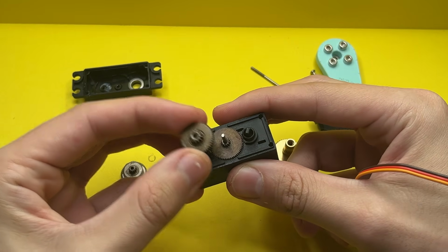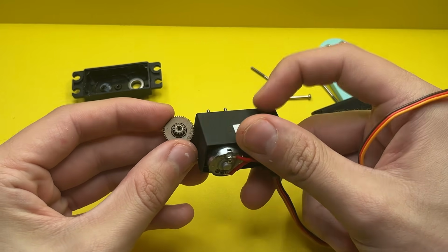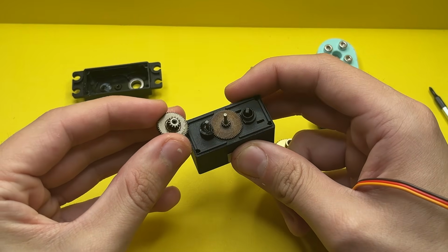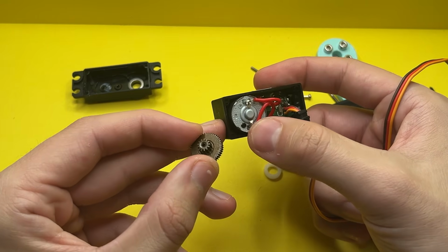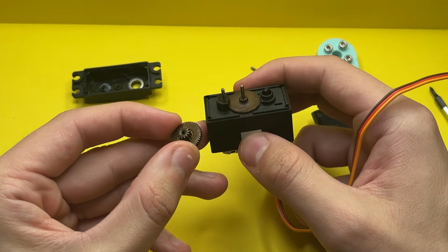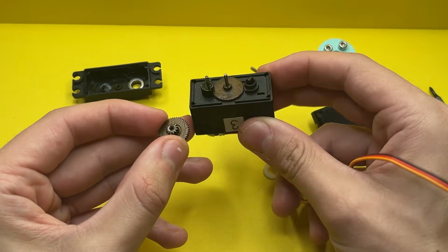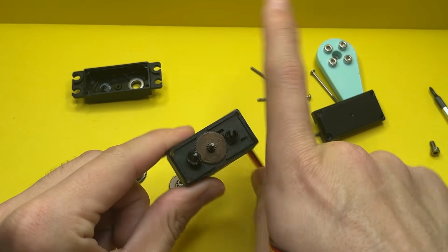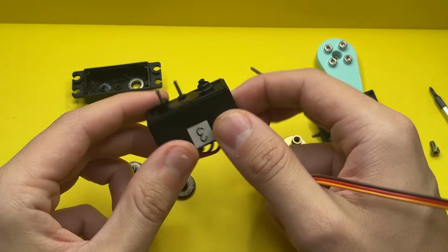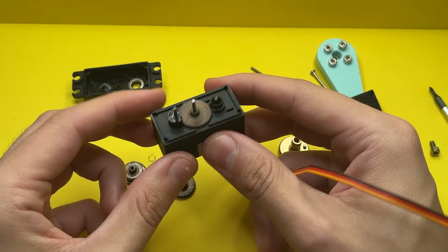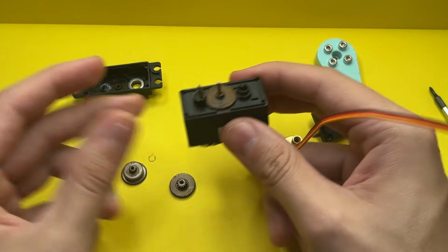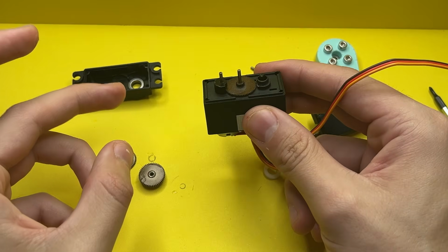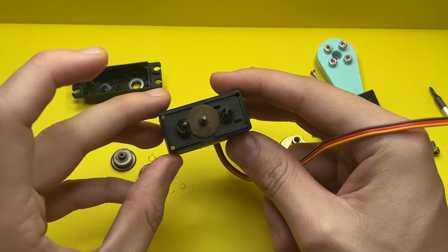What these gears do actually is reduce the speed of the motor and increase the torque substantially. So these small motors are great for spinning fast, but they're not really torquey, and as you've seen with the servo motor, what we actually want is small movements, like 180 degrees or 90 degrees, and we don't need it to be too fast, but we want it to be as strong as possible, and that's what we're accomplishing with the gears. How that's all calculated, you'll see in one of the next clips.